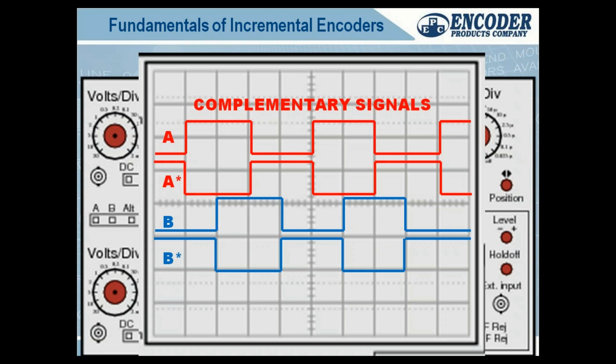Incremental encoders, that is the number one downside to an incremental encoder. It just spits out pulses. There is no memory. There's no serial communication. You turn that thing off and move it and turn it back on, it's just going to spit out A and B again. So you will lose position if you lose power. And a lot of CNCs that ran with servo motors that had incremental encoders, well, that's why when you lost power and that Z-axis dropped before the brake kicked in, you had to turn that machine back on, and the first thing you did was a machine zero because you lost position.